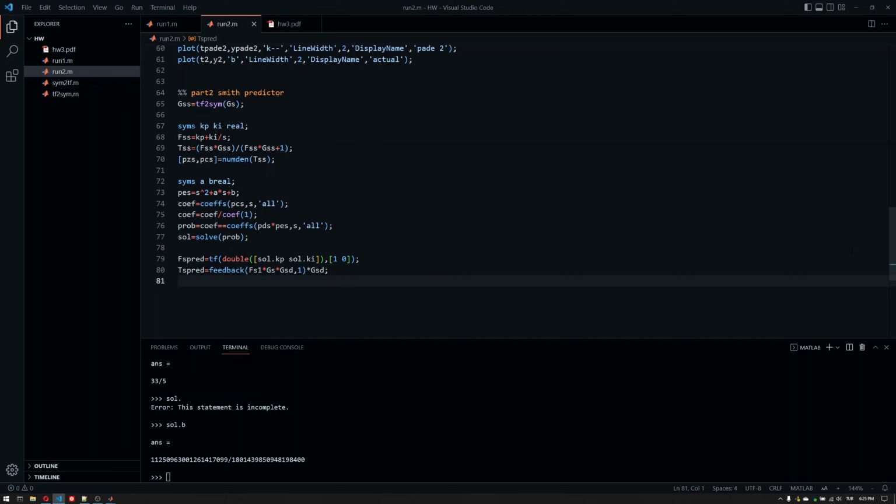There will be delay, but the remaining part is just a basic minimum phase transfer function. And if I design the PI controller for the minimum phase of the open loop, I end up in the closed loop, which is basically the minimum phase closed loop, shifted with 2 seconds delay, and that's basically it.